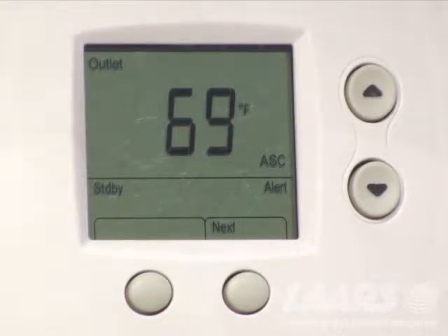The very first thing you want to do is get in and confirm your central heat set point. Your central heat set point is the desired temperature of your heating system. Different heating systems have different settings, such as in-floor radiant is going to have a lower temperature. Hydro air systems may be running around 160, and baseboard heat may want to achieve 180 degrees. So let's use the example of baseboard heat for 180 degrees.